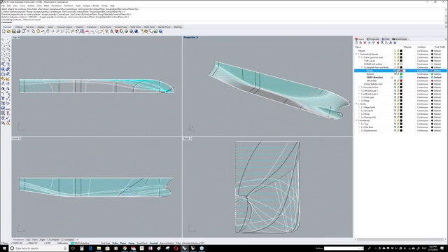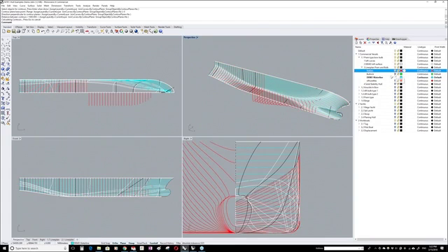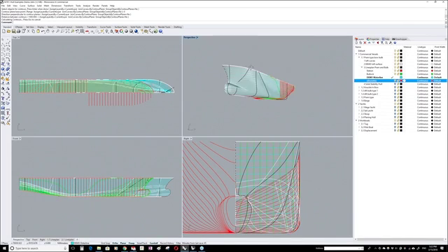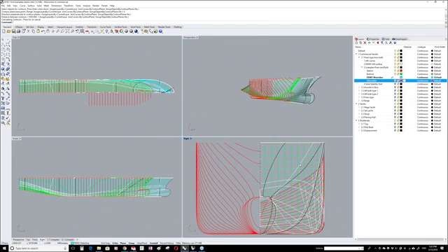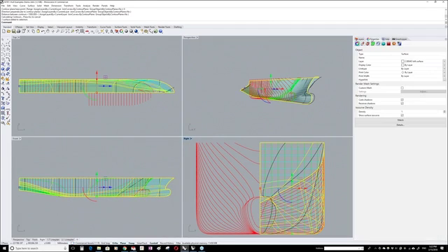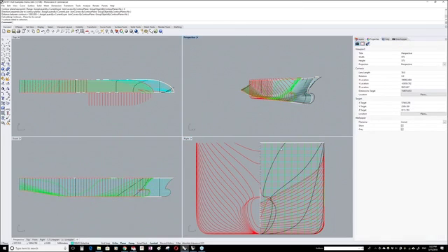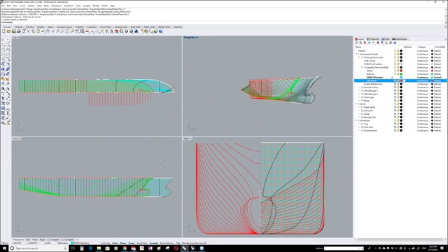And I've already prepared the buttocks. Here you can see, for example, I can make these visible. So now you also see the loft lines, but you see the lines plan, and you can check that as well. And you see that I've lengthened the ship, and I've made the waterlines of the lengthened part. Sorry for that, but I think you understand the idea behind it.